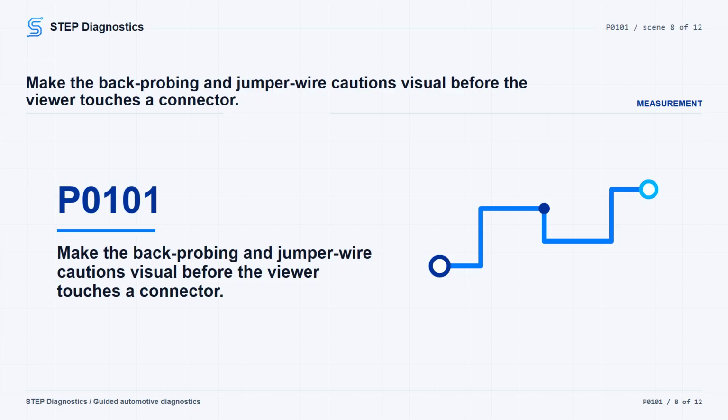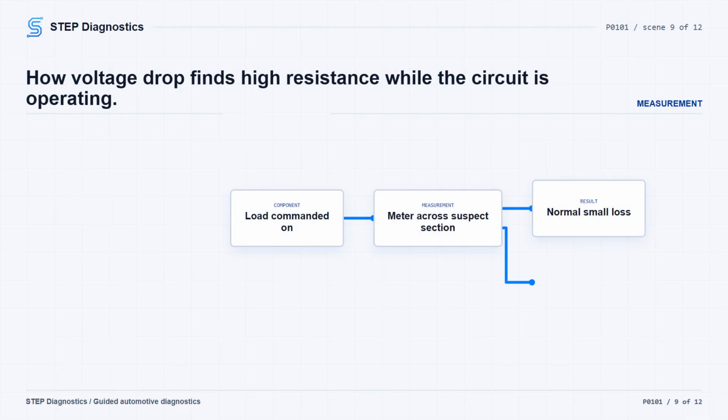With jumper wires, always use fuse jumpers. The recommended universal testing jumper wire fuse is 5 amperes or less. Flex probes help prevent terminal damage, but they are not meant to carry high current greater than 5 amperes.